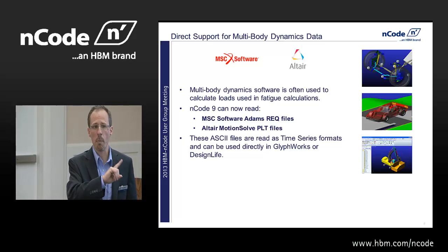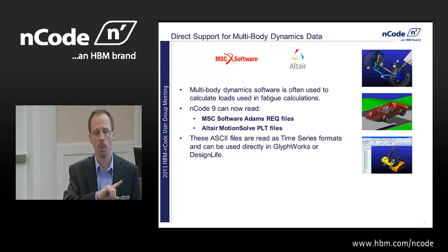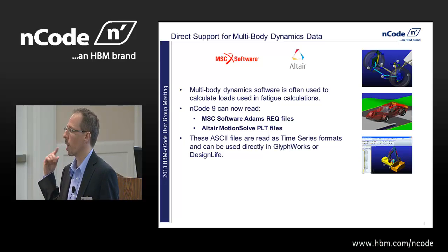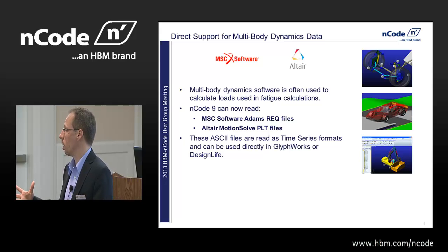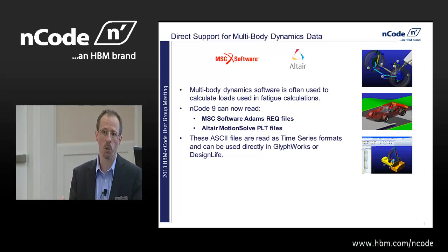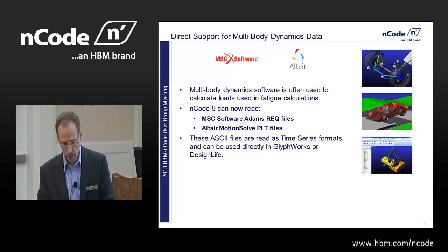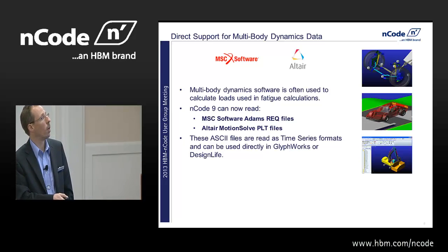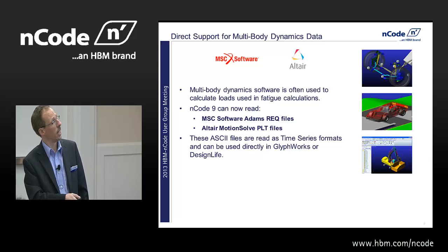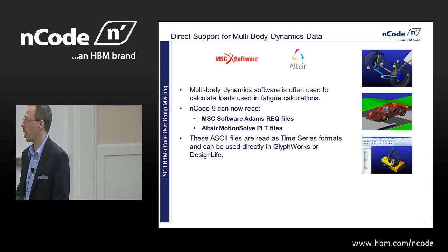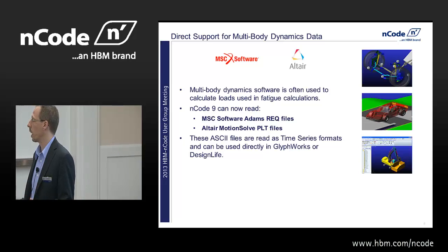And so it's become quite common for durability simulation to use multi-body dynamics simulation to input what you can measure and what you do know, maybe a road surface, and then calculate what you can't measure, things like internal loads on a component. So we added support in this release to read directly the output files from MSC's Adams software and also Altair's MotionSolve results files. So we can read those files now directly in GlyphWorks.